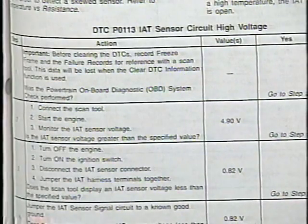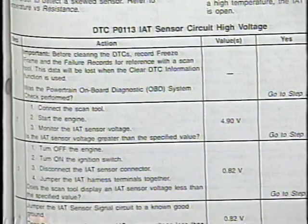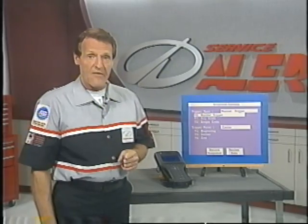Now, when do you need Snapshot? When you're diagnosing a symptom for which a diagnostic trouble code or DTC has been set, you follow the diagnostic chart for that code, of course. But when there's a history code that isn't current when the car comes in, or when no codes are set, and when there's an intermittent symptom that you may be able to recreate, then Snapshot can be a big help.